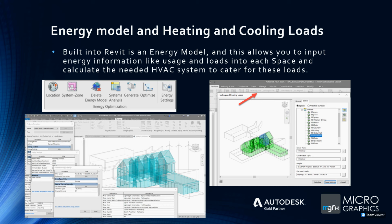So it takes all these factors into consideration and provides a report on the loads needed, or the liters per second. Obviously it provides a report on the loads of each space, but it also provides an estimate on how many liters per second of cool air or hot air it needs to combat these loads.